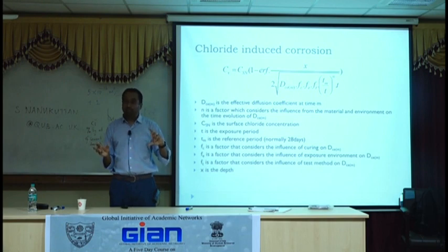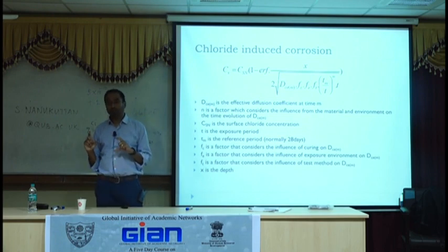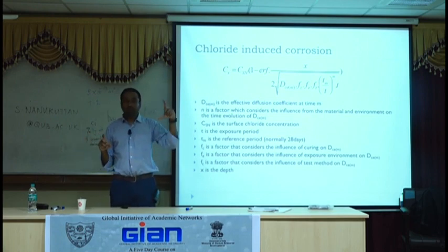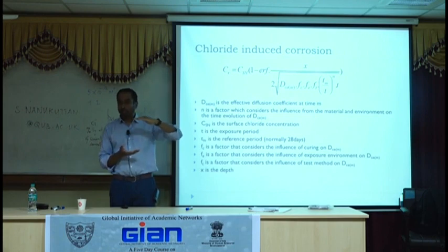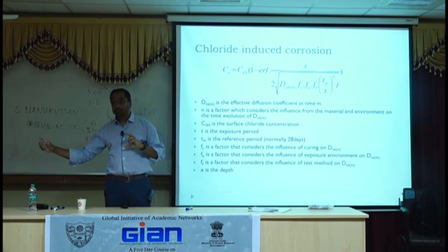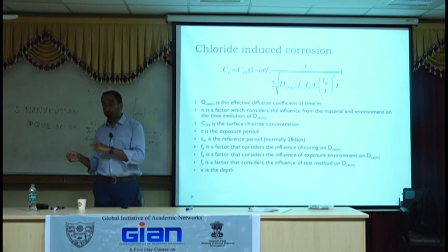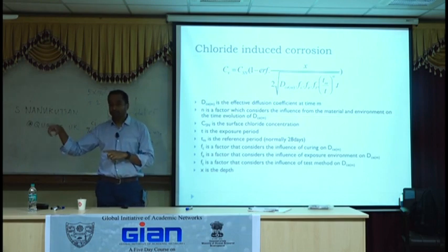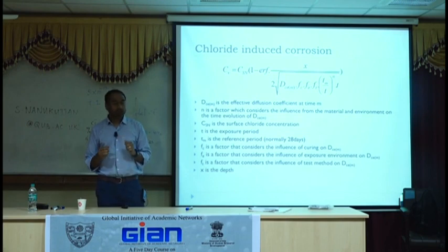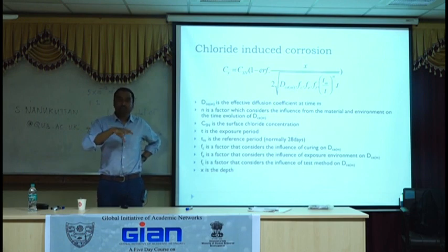But the Portland cement we decided to cure for 2 years, and the blended cement we also cured for 2 years. What we found is the reduction due to curing in Portland cement was significant. It doesn't reach the same as the blended cement by any means, but it has the potential to go closer to it. It clearly was better than the 28-day values. Let's see if I can pull up the presentation and you can have a look. So curing does have a role to play. In the old days, I think people would have cured concrete much longer.